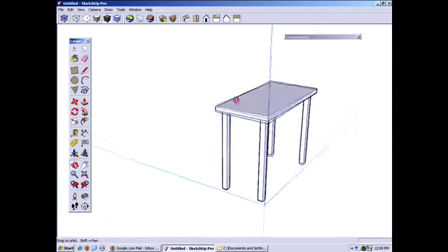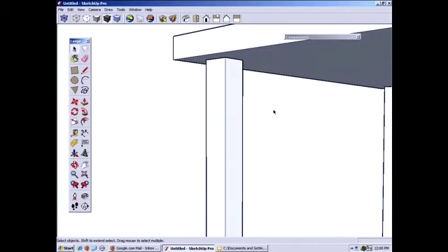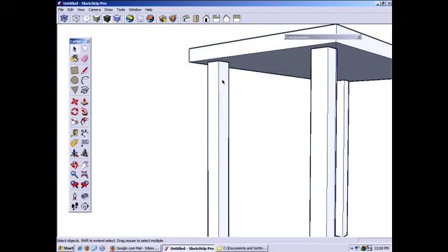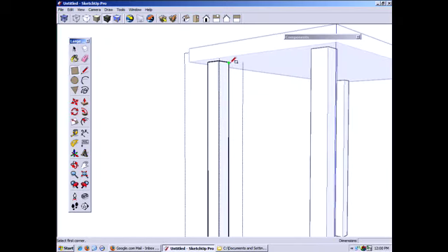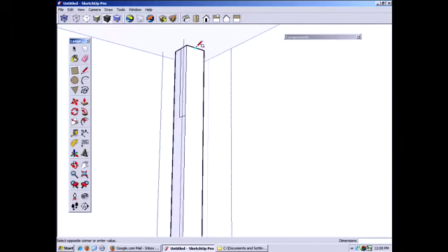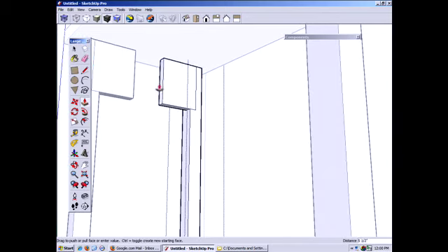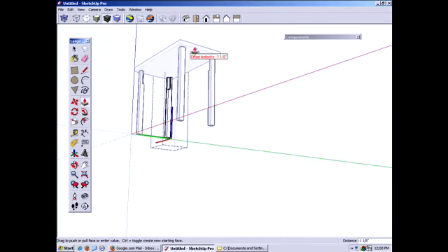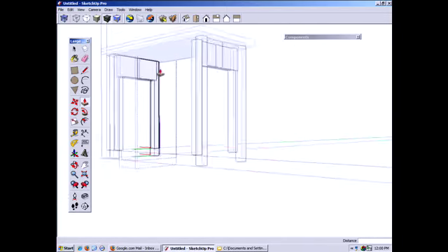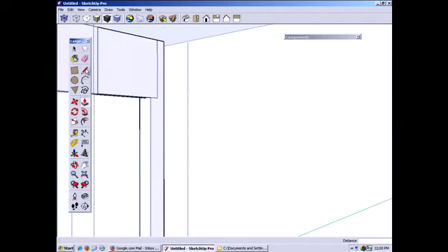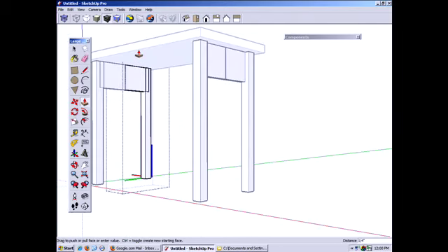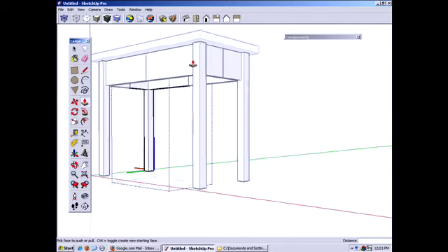It means that we can now come in and add a lot of detail by editing just one of these components. So I'm going to double click, edit this component. Let's say we'll go from the midpoint, add a skirt here, pull this out, and I'll just reference, say, the midpoint of the table. And then, oh, I lost my line, that's okay. I'm going to pull this out and reference the midpoint of the table here.